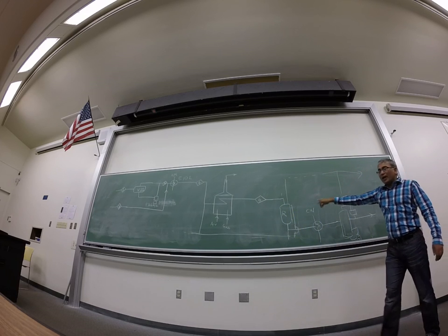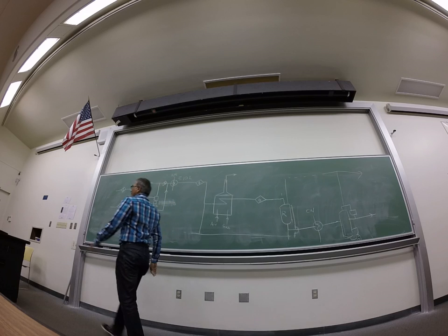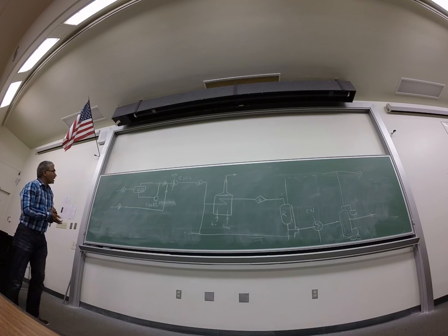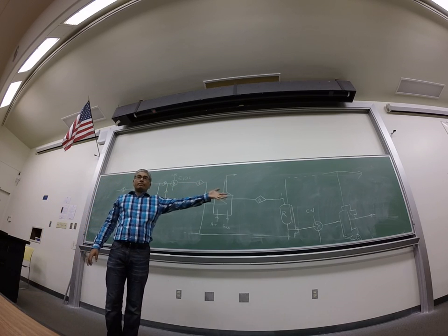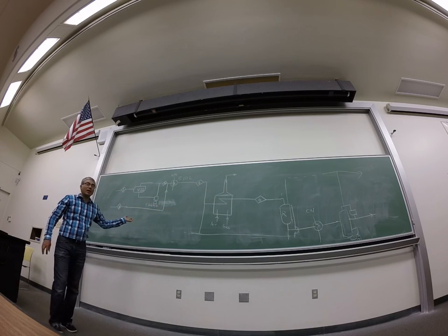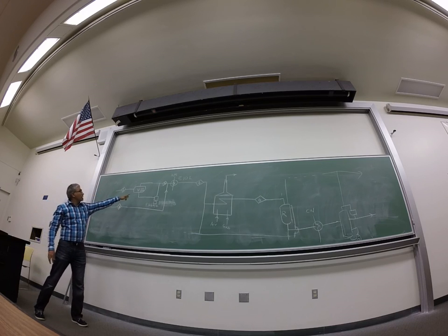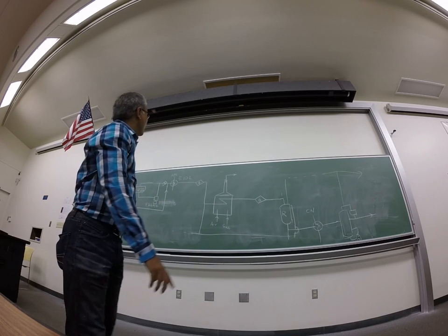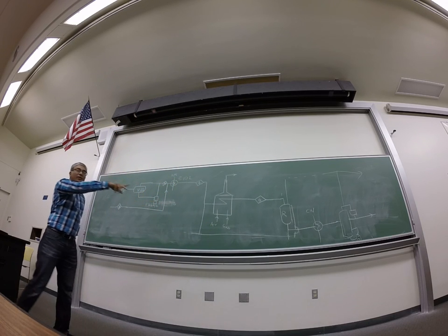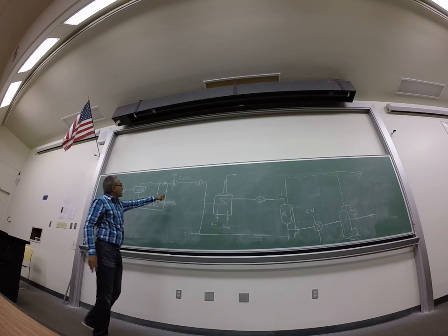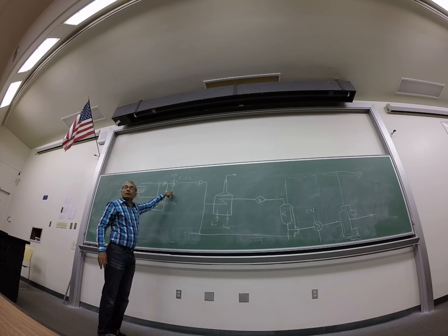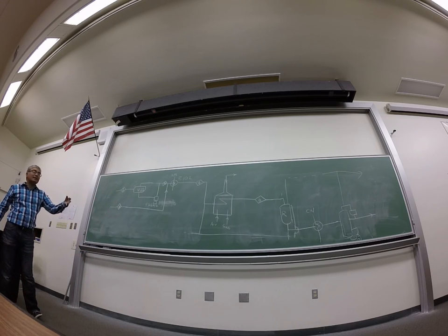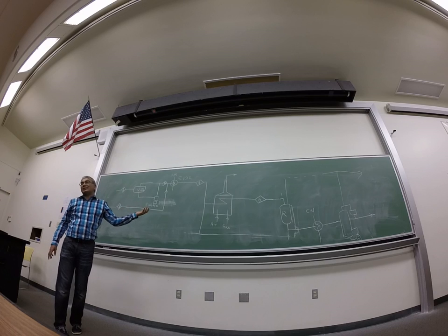Okay, so this is not actually exactly complete. I'll upload this, and you can see. But the important thing is, what are the important things? The important things are that now we're actually putting every equipment in, and what type of equipment it is. Okay, it's a heat exchanger. It's just a vessel. So really now you have a better idea of what every equipment is. We're putting in numbers for every stream, right? Also, we're indicating all the utilities, right? And then, of course, you have to put in a few more details, like all the mass balances. And once you put in all the mass balances, that's essentially a process flow diagram.